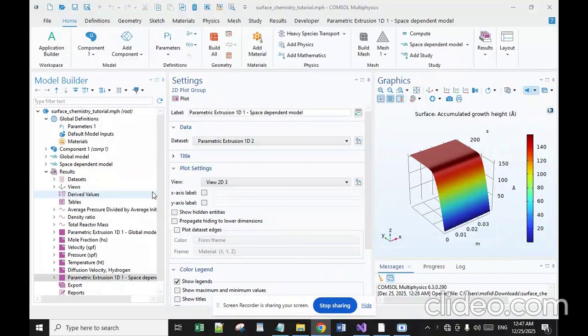The next one is microwave plasma assisted CVD. The next one is plasma enhanced CVD, which utilizes plasma to enhance chemical reaction rates of the precursors. Plasma utilized CVD processing allows deposition at lower temperatures, which is often critical in the manufacture of semiconductors. The lower temperatures also allow for the deposition of organic coatings such as plasma polymers that have been used for nanoparticle surface functionalization.